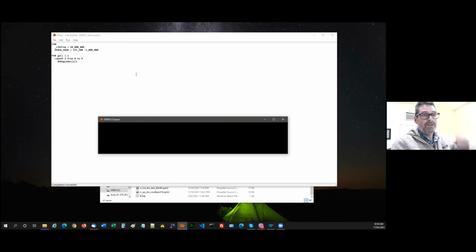So what we need to do, here Lachlan wrote, FT Prog lets you set PID, ID, and FTDI chips and invert DTR, etc. So I think this is what's happening. We're configured differently. Same chip, but we configured it differently.